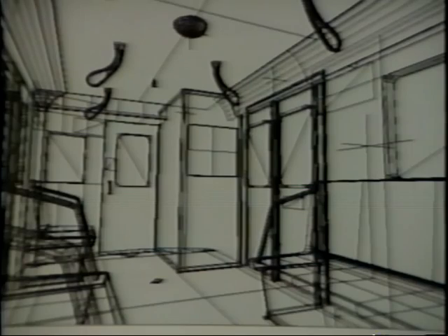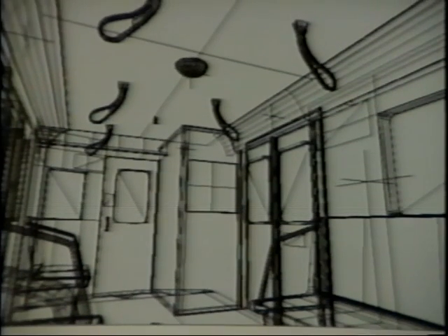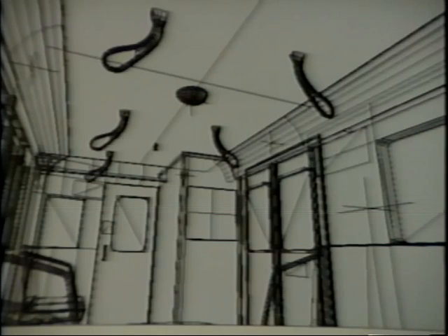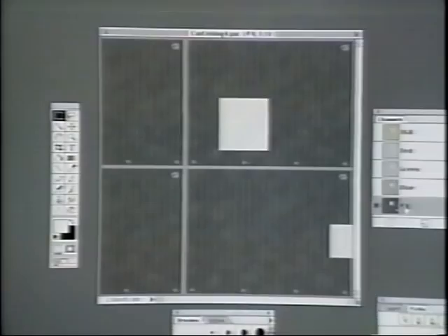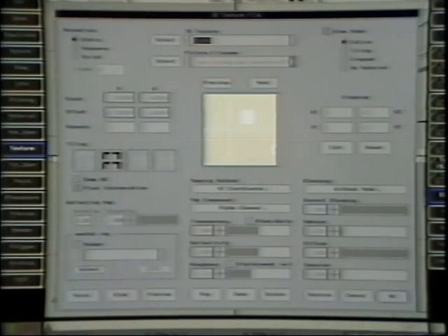If we look up at the ceiling, we'll see a map with another use for its alpha channel. The ceiling has a reflective material, and the reflection is distorted by a bump map. The actual ceiling texture was created from scratch in Adobe Photoshop, with a separate image for the roughness or bump mapping stored in the alpha channel. The brighter parts of the alpha channel will be shaded as though they were higher, and the darker parts lower.